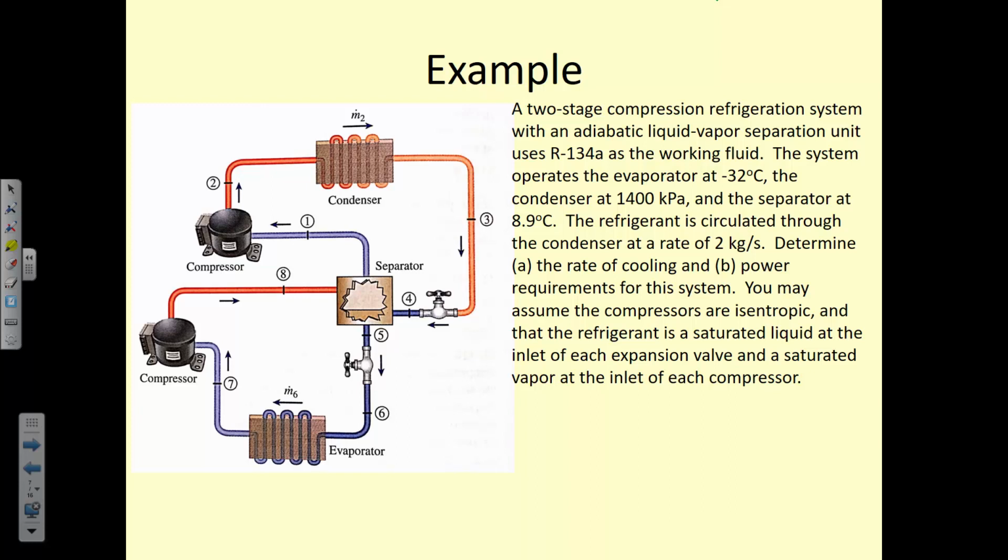Alright, so now we're to this example. I'm going to try to make this a little bit quicker. This one's an easier problem anyway. So looking at this, what type of a device is it? Before you even start solving it, making that recognition that it is a what? A refrigerator. How's a refrigerator different? The QLs are going to be different, opposite of what a heat engine would be. And you have a work input, a net work input.